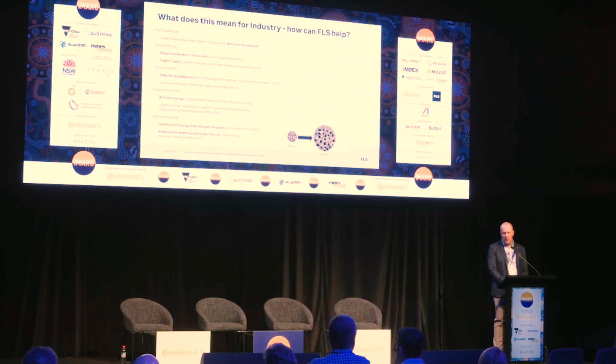So taking our grind size from something like 150 micron, which is typical for a copper concentrator, and seeing if we can do flotation at something a little bit more coarse, let's say 350 micron. That's kind of a paradigm shift in the bigger scheme of things, because our whole industry is rigged around flotation at 150 micron.